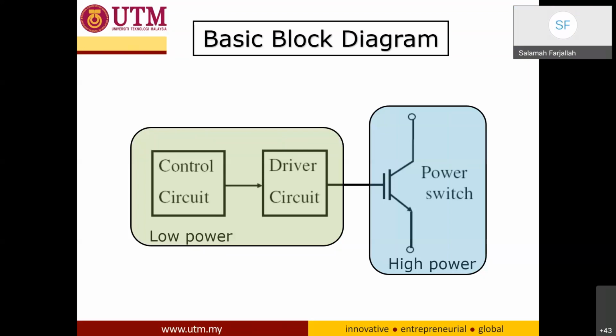No. What is the requirement to turn on and turn off the MOSFET? Voltage at VGS. Yes, the voltage at VGS must be how many volts? 15. Yes, 15 volt to turn on, and to turn off must be 0, right? Yes. Okay.